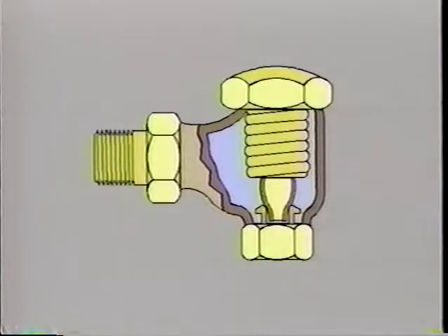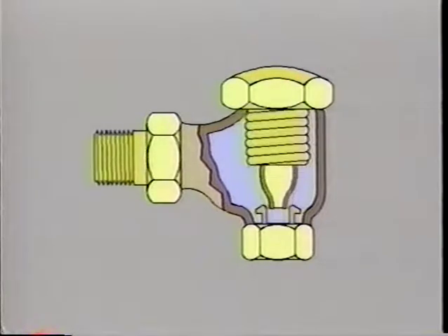The thermostatic steam trap has a bellows filled with a fluid that boils at steam temperature. As the fluid boils, vapors expand the bellows to push the valve closed. When the temperature drops below steam temperature, the bellows contract to open the valve and discharge condensate.